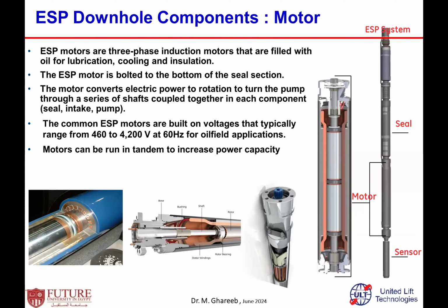Generally, the commonly used one is called an induction motor. Even if there are different types of motors on the market now, in general, in more than 85 or 90% of wells worldwide, the motor type is the induction motor. It's filled with oil for lubrication, cooling, insulation, and so on.